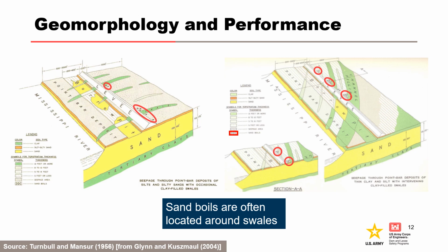In the figure on the right, seepage is particularly concentrated in sandy ridges, where the edges of swales intersect the levee toe in instances where the long dimension of swales is parallel to the levee or intersects it at a small angle. Clay plugs and channel fillings are also depicted and concentrate seepage with a similar effect, but considerably accentuated owing to their greater thickness and width.